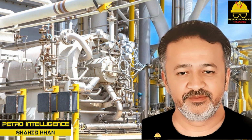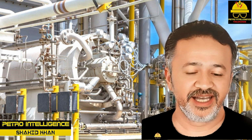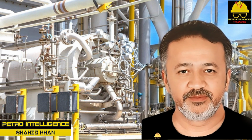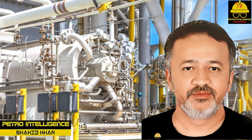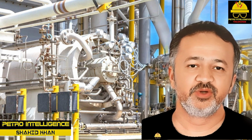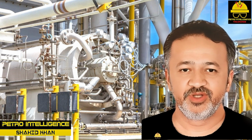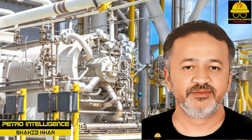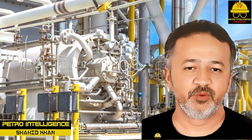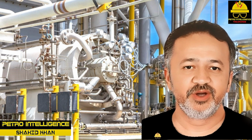Compression ratio. Compression ratio is defined as the ratio of discharge pressure, PSIA, to suction pressure, PSIA. Frequently, the desired discharge pressure is very high, over 100 times that of the inlet pressure. When a gas is compressed, the temperature of the gas increases. If a gas was compressed in one stage to a pressure 100 times that of the inlet pressure, the gas temperature would be extremely high. Multi-stage compressors, with cooling between stages, are used to develop high pressures to allow for the heat of compression.